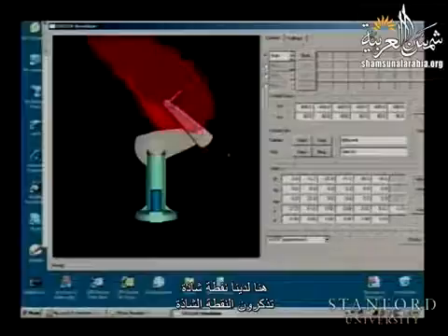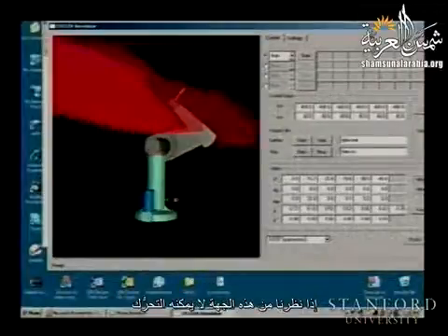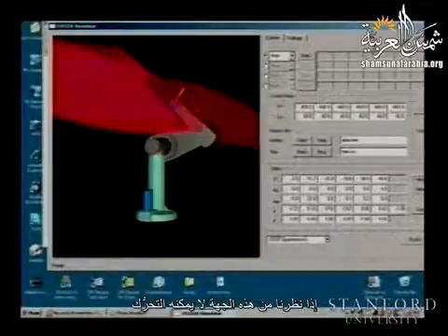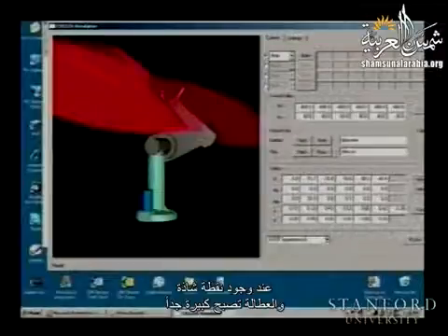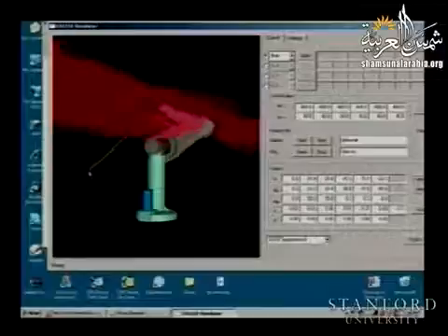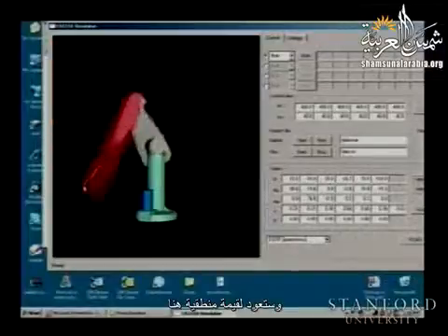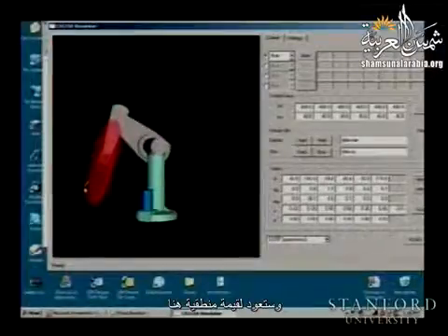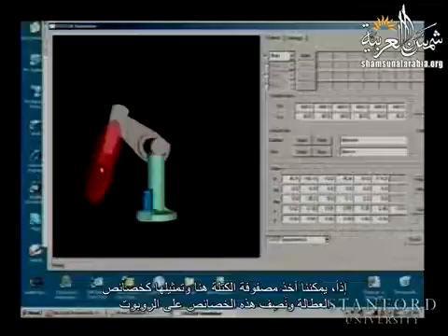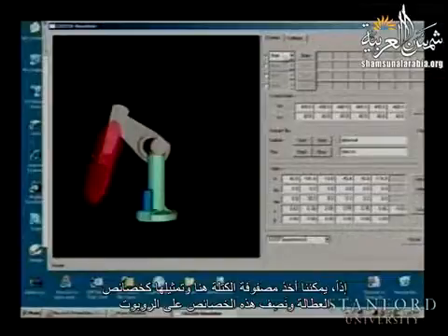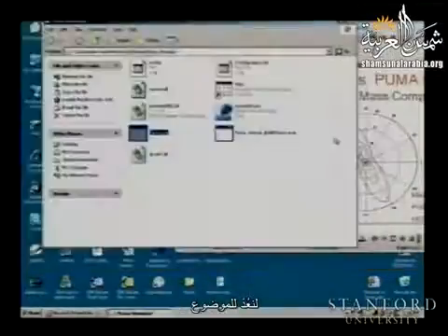You remember the singularity here. And if we look at it, in this direction you cannot move when you come to the overhead singularity. And the inertia becomes very, very big. The inertia goes back to a reasonable value in here. So we can take this mass matrix and represent it as the inertial property and describe those properties on the robot. So let's go back to.